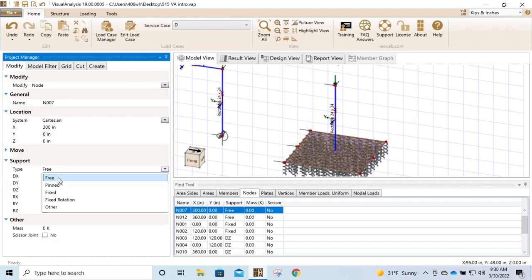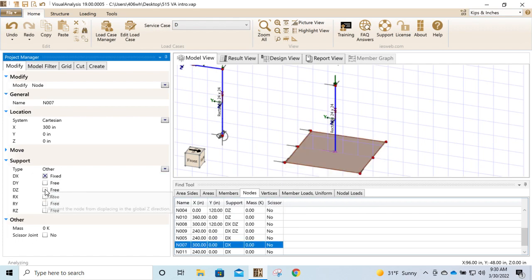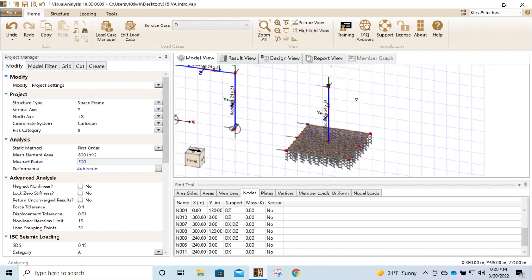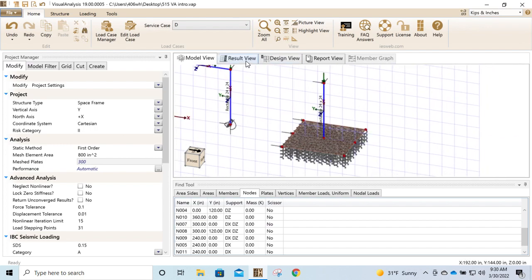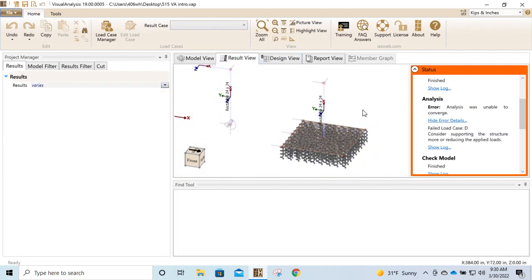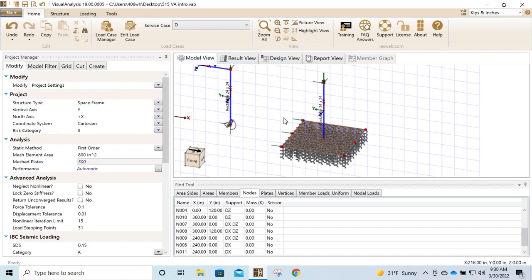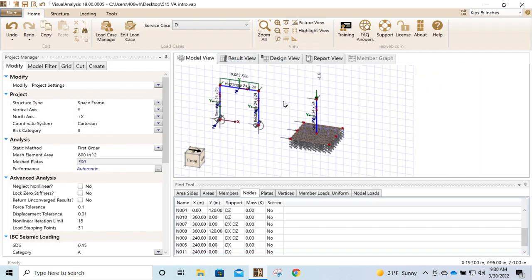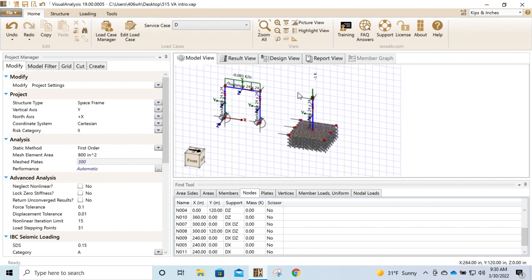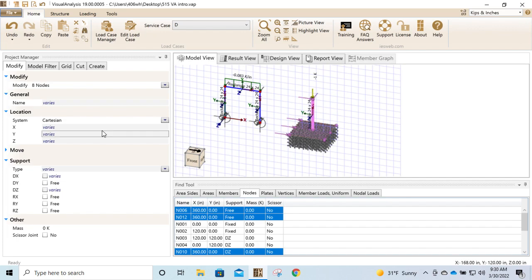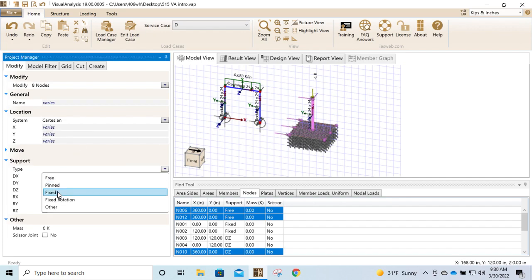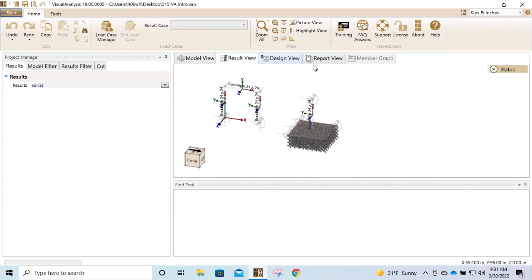We'll talk about this when we talk about troubleshooting models, but a lot of times the easiest way to do some of that is to overfix a model and then work yourself backwards, right? So I could go through and we could fix every one of these nodes and then come back through. Well, I'm just gonna do that right now. Fix every one of these. Now it runs. It's a beautiful thing.